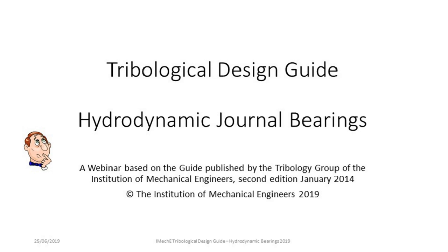Hydrodynamic bearings have been around for a long time. I suppose the recent development, we're all concerned about loss of energy, making these things as efficient as possible, and therefore reducing the viscous losses. The easiest way to do that, of course, is to reduce the viscosity of the fluid. But the penalty you pay is thinner films. That means you have to have more accurately machined components, smaller clearances, and better surface finishes, and so on.